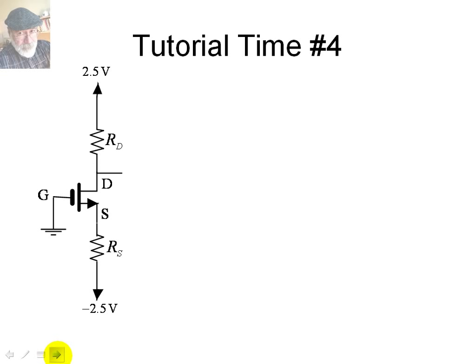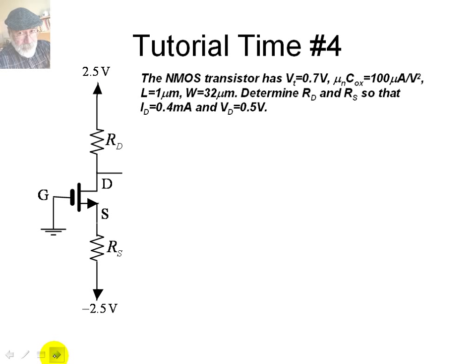Consider this circuit here. The gate has been grounded. It's connected to the reference node, and we have a power supply with 2.5 volts on the top and negative 2.5 volts on the bottom. We are told we have an NMOS transistor, shorthand for an N-channel MOSFET. The transistor is specified by a threshold voltage of 0.7 volts and enough data to compute Kn, the conductance coefficient.